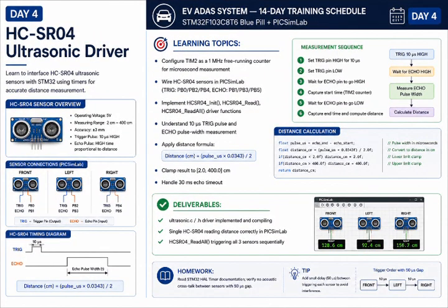And coming to day 4, I interfaced the HC-SR04 ultrasonic sensor with STM32. I used timers for microsecond measurements and calculated obstacle distance using echo pulse duration. Three ultrasonic sensors were connected to detect obstacles from the front, left, and right sides, which forms the basis of the ADAS system.